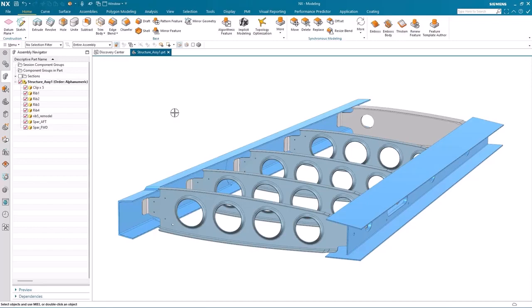In this demonstration I'd like to take you through a brand new validation tool in the December 2023 release of NX called NX Corrosion Analysis Indicator. It looks at providing corrosion analysis of component parts in an assembly based upon their proximity and also the assigned materials and coatings, and it predicts the corrosion risk rate based on the galvanic properties of these assigned materials using the latest industry approved methods. So let's take a look at it in more detail.